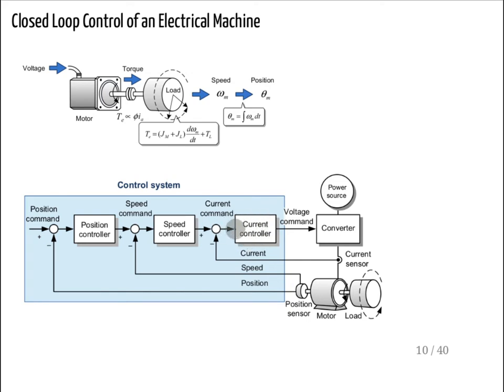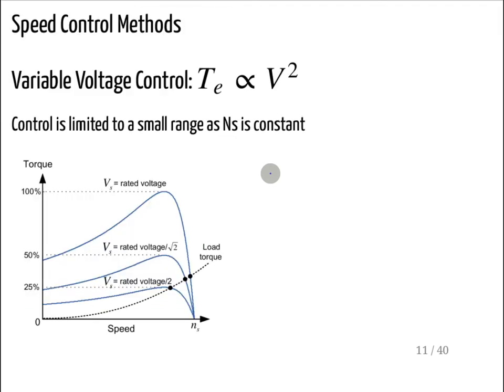Then the current controller calculates, in order to give that amount of current, what voltage should I apply to the motor. Then the voltage command is sent to the power electronics or that kind of controller. And actually you can measure those things, and you can have some current sensors in the system. And again, as you see in control theory classes, it is possible to get a transfer function both for the mechanical system, electrical motor, etc., and you can design the best controller.